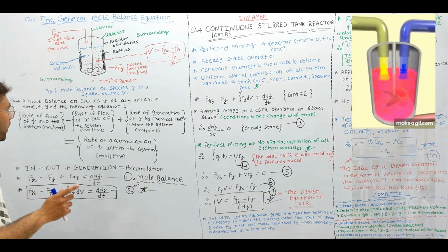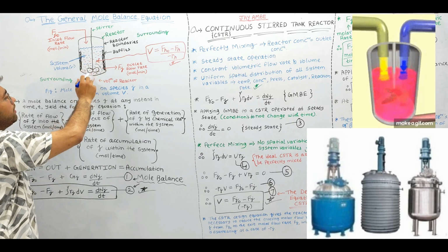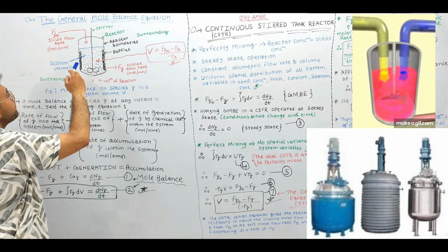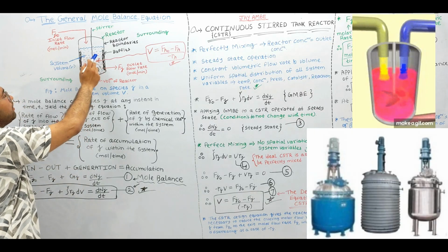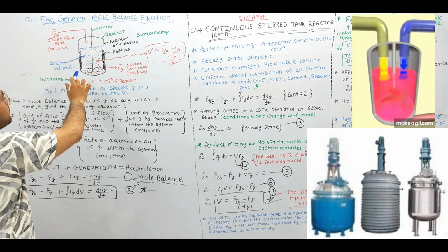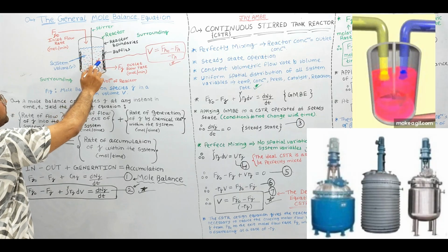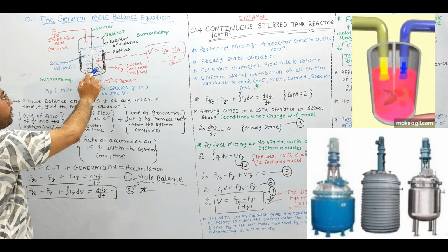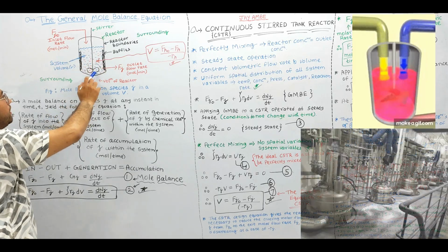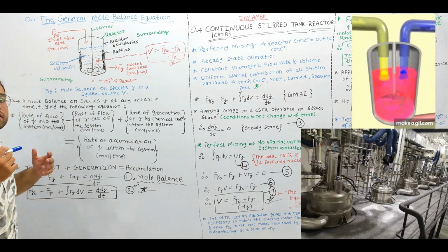By using the stirrer and agitator, we have uniform mixing, which means we have a uniform spatial distribution of all system variables, like temperature, concentration, pressure, and catalytic activity, throughout the entire reaction volume. So at each and every position and time, we have the same concentration, right?